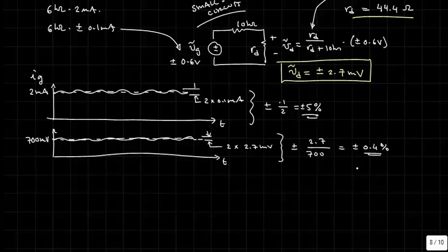In fact, it's far less. And so you can have a reference voltage to be used however you want in your circuit that is fairly immune to changes in the supply. That is an important need in electronics. Having voltage references is very important, and we'll see more of that perhaps in the rest of the course.